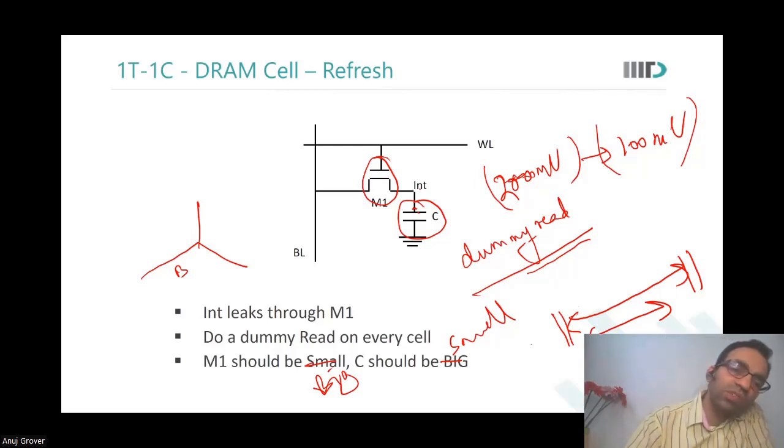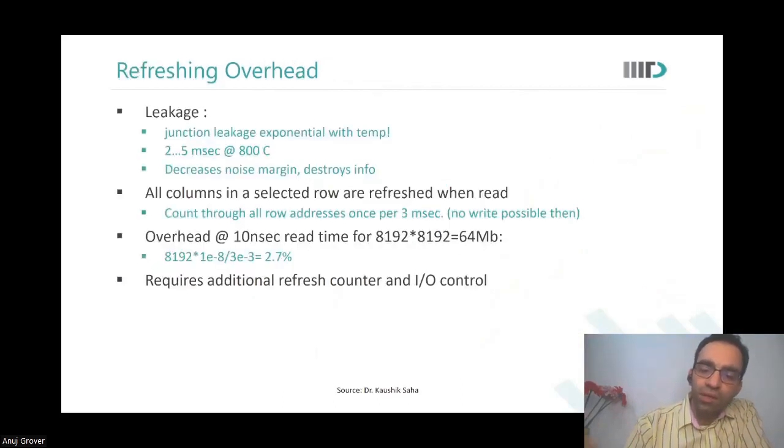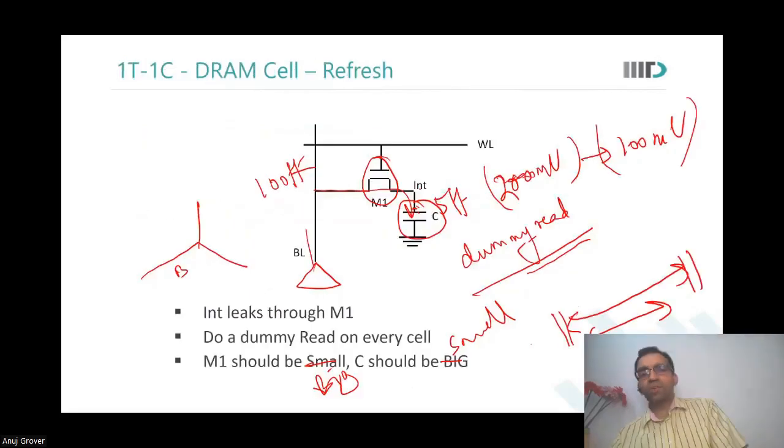Oh, okay. So see, you finally would have the sense amplifier driving the bit line and the internal node. Only one internal node is going to be visible to the sense amplifier. This capacitance is 100 femtofarad, let us say. This capacitance is 5 femtofarad. So instead of 100, it appears as 105 femtofarads. Not a very big deal, no?